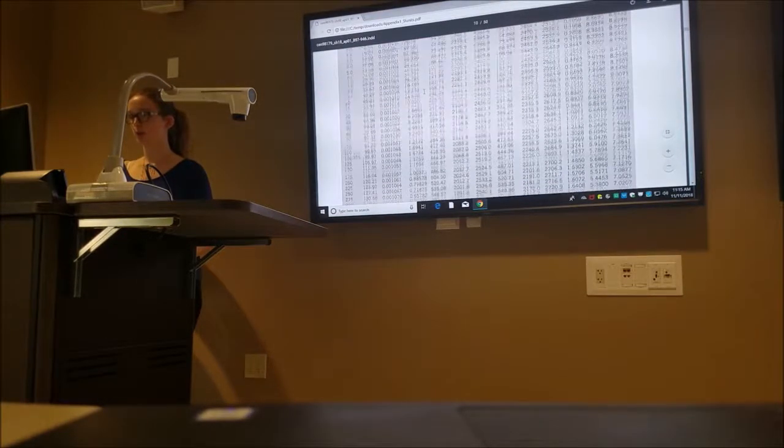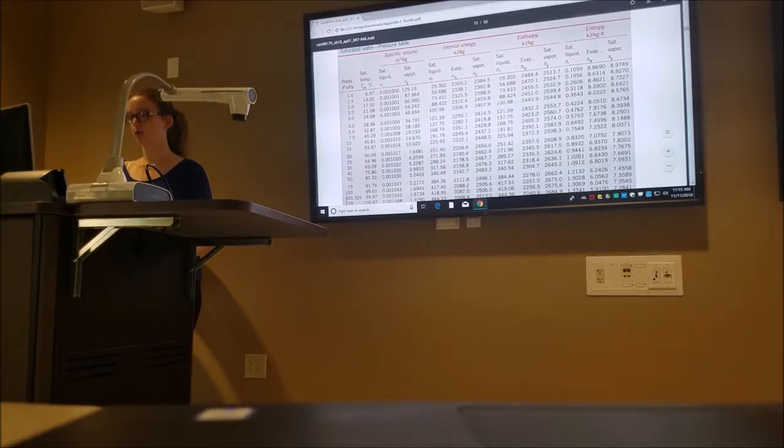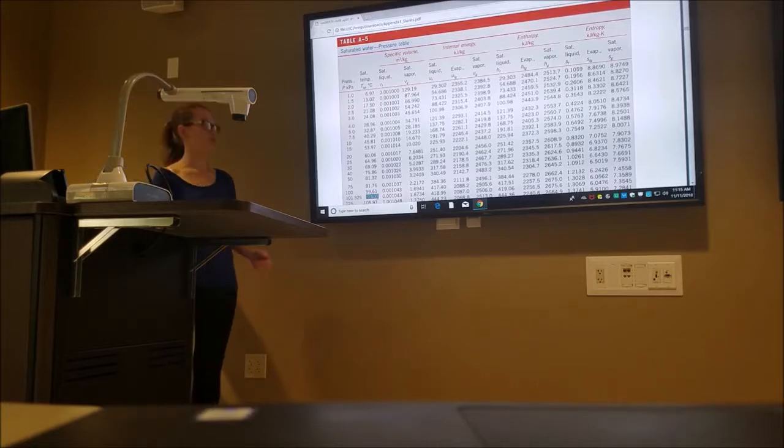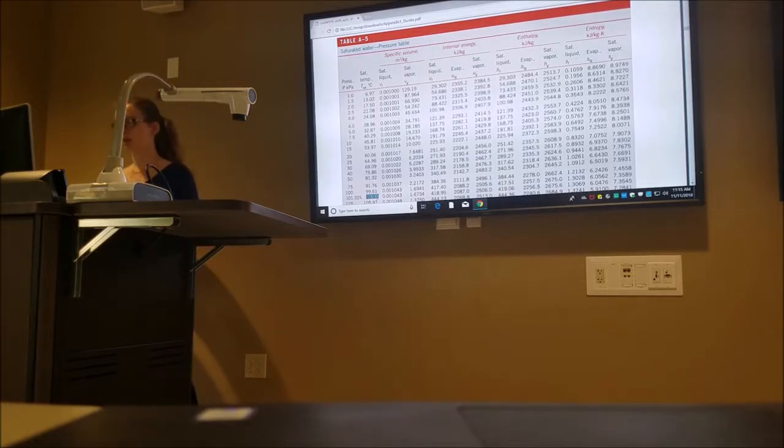So we go to where the pressure is 101.325 kilopascals, because that's atmospheric pressure. Here we can see that the temperature of the vapor will be 99.97 degrees, which is the answer to the first part of the problem. And then we can get Hf and Hg. So we see Hf is 419.06 kilojoules per kilogram, and Hg is 2,675.6 kilojoules per kilogram.